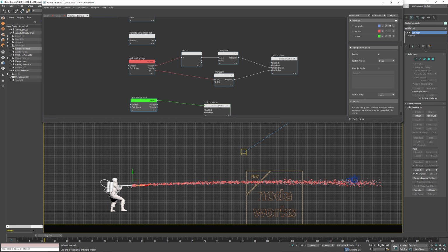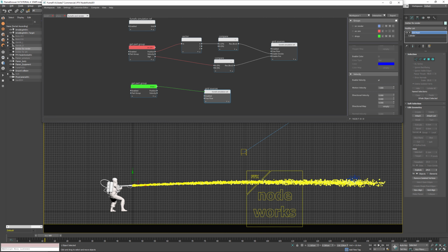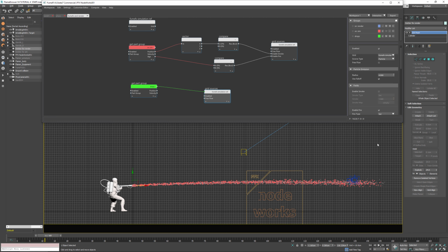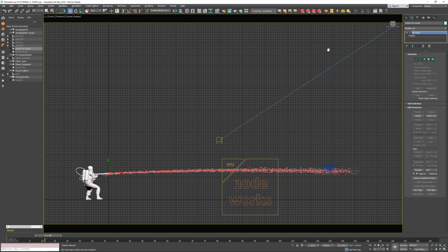Next we have those drop particles. They are also grid sources, but since there are fewer particles, I'm using a larger radius of 4 and enable fire and temperature. However, smoke emission is disabled, as I'm going to set this up through the FumeFX simulation, as it's going to create smoke when the fire burns, and motion velocity scale factor is 1. Now we're ready to go for the FumeFX grid simulation.